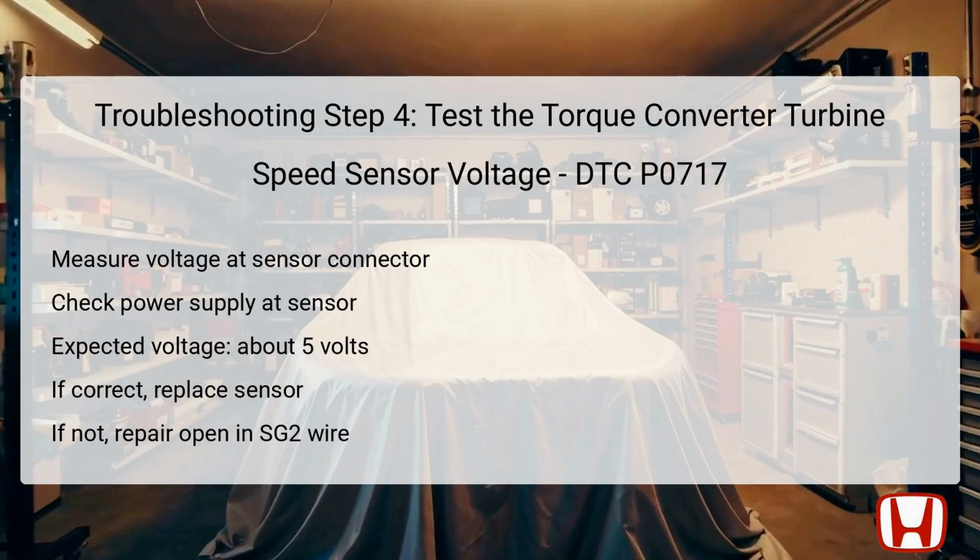This step focuses on confirming the sensor's operational voltage. Disconnecting the sensor connector allows for measuring the voltage directly from the sensor terminals. The measured voltage between test point 1, which connects to the sensor's signal or power wire, and the common ground should be around 5 volts.